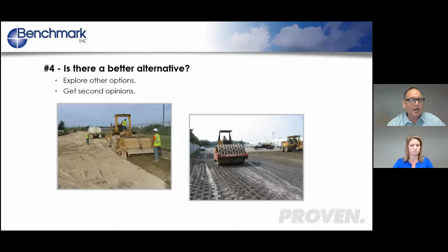Just because the contractor comes to you with a solution to a problem that came up, explore other options. Maybe there's a better, more cost-effective way to do it. And where we typically see that is on large parking lots or roadways, when you remove the pavement and all of a sudden it's not just a small isolated area like we showed in the previous example. The whole area maybe needs to be stabilized and it's just not cost-effective to dig it out.